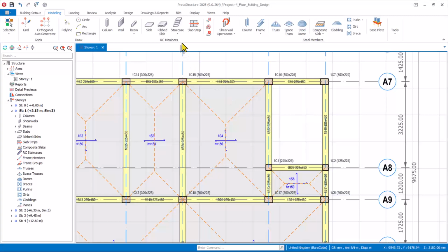For the staircase, you use this staircase provision. In staircase modeling, we have 3 options. First is by selecting the area: just pick the area bounded by the beam, or in the panel, or in the stair room. The second option is using 2 diagonals: pick the first point, pick the second point. So let's use this second option.